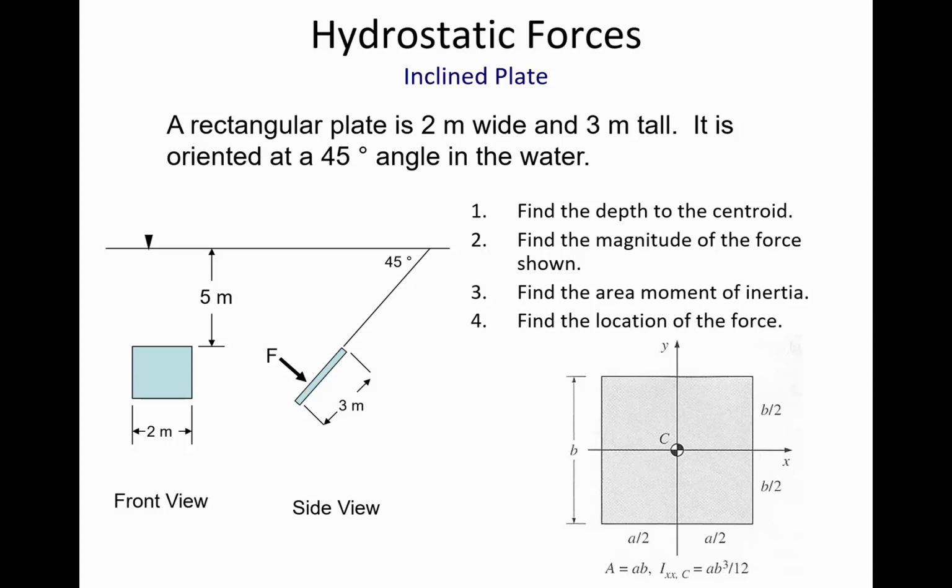Okay, so he's asking about the water temperature. Yeah, it doesn't say the water temperature, and since it doesn't specify, let's just use that gamma is 9810 newtons per meter cubed. That's the default unit weight that will be applied anytime a specific temperature isn't given.